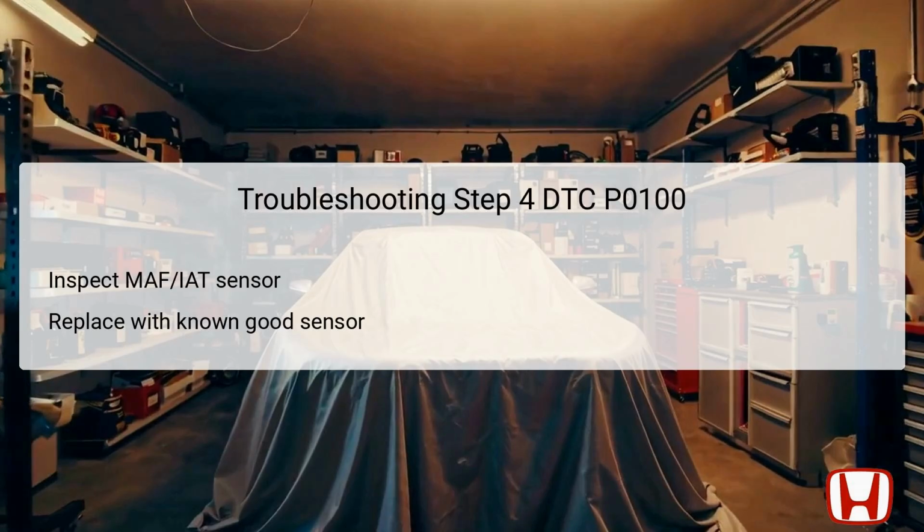Because there is no direct testing method available for the MAF sensor, the recommended approach is to replace it with a known good sensor. This step is essential for isolating the problem. If you install a functioning MAF sensor and the vehicle operates correctly without triggering DTC P0100 again, it indicates the original sensor was faulty. If the issue persists after installing the known good sensor, it suggests that other related components or circuits may be at fault. Being methodical in this approach helps to effectively narrow down the issue and avoid unnecessary component replacement.